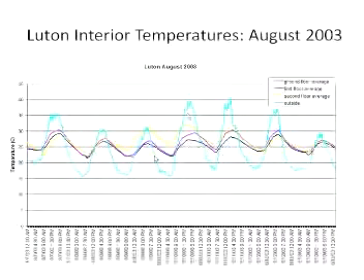This line here, the blue line that you can see, is the actual measurements we made of outside temperature. Each one of these cycles is one day, and you can see in the afternoon in the summertime in August, the temperature got up to 40 C, which is above 90 degrees Fahrenheit. The other lines in here, though, show what the interior temperatures are on different floors. And because of the thermal mass, you can see that the air temperature inside the building is about 10 degrees centigrade lower than the temperature outside. So again, the thermal mass, if properly controlled, can help to establish very comfortable conditions within the space.